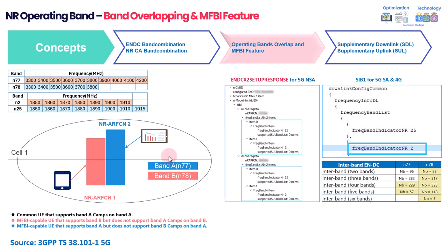And in case, for example, you have a carrier aggregation combination, let's say N77 and N78, the user will still be able to read both. Let's assume that you have two frequency bands in your network, one for N77 and one for N78, and you're configuring this one from 3500 to 3.6 or 3.3 to 3.4. So the MFBI will let the user read both of them. For example, let's assume both of them as N77. So if the carrier aggregation user is only supporting N77 plus N77, in this case, the user can enjoy the services of carrier aggregation or even the initial access.